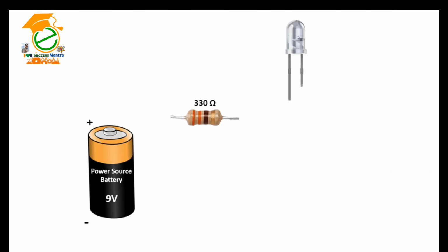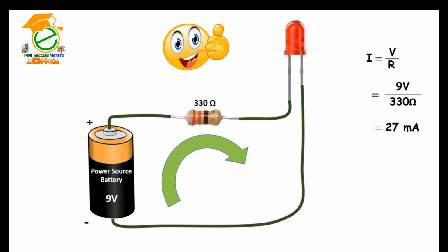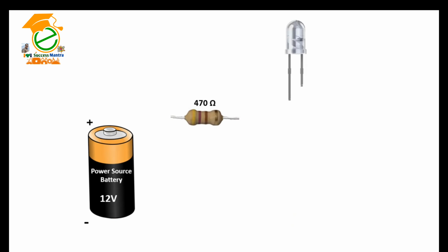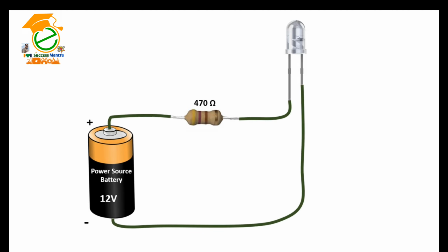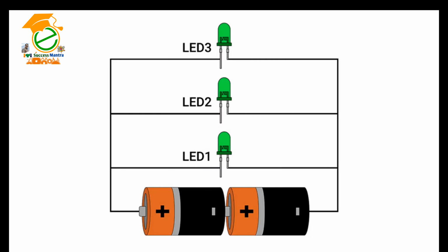Like all diodes, LEDs create a voltage drop in the circuit, but typically do not add much resistance. In order to prevent the circuit from shorting, you need to add a resistor in series. You may be tempted to wire LEDs in series, but keep in mind that each consecutive LED will result in a voltage drop until finally there is not enough power left to keep them lit. As such, it is ideal to light up multiple LEDs by wiring them in parallel. However, you need to make certain that all of the LEDs have the same power rating before you do this.